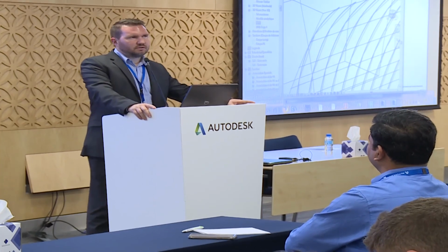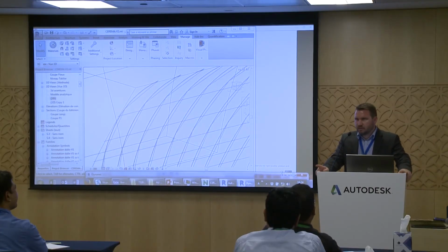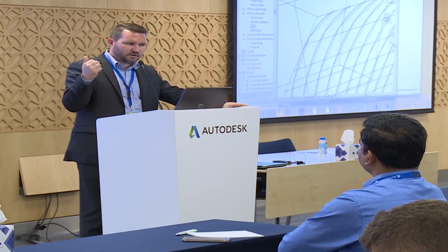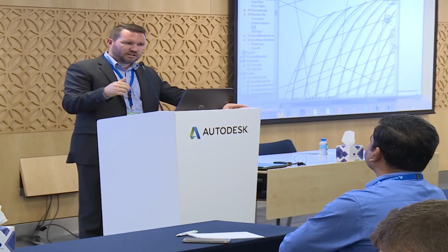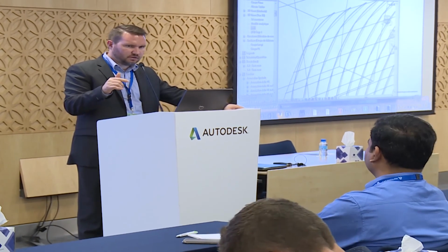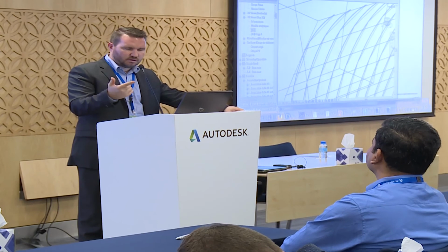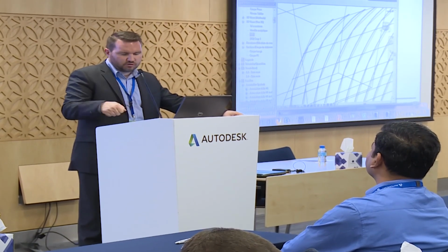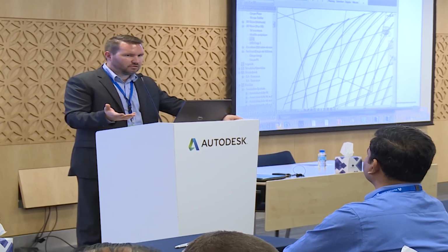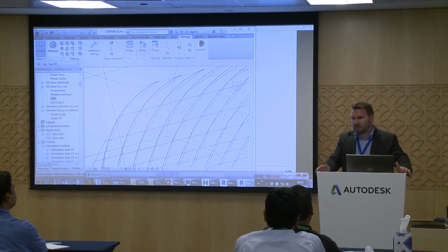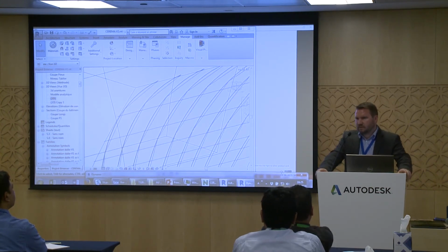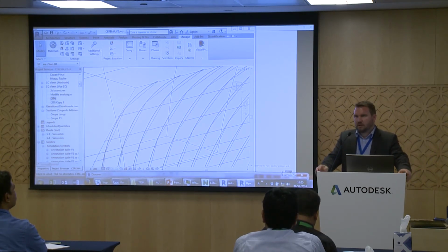Yeah, because sometimes the reinforcement we have, I don't know if it's a long beam, but usually it comes from the deflection, because in Robot we increase reinforcement due to deflection, and usually when you do the manual calculation, you don't take it into account. And I don't know if ETABS does this. I don't know if it's not a long beam. Usually they know, but I think you should come back to us if it's important for you, because I've done some verification, and I found the same as manually, but I won't display it here.